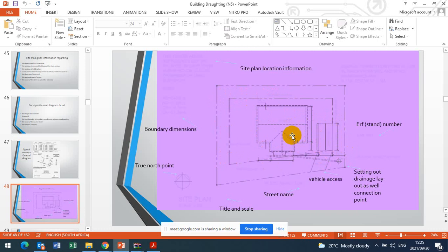So you must make sure you do this, and this is the roof edge layer. You see the dashed lines around the house. It is the roof edge. And this roof is called the Gable-End Roof. G-A-B-L-E. A gable-end roof is a pitched roof. It slopes only on two sides, this side and this side. Here it's a gable end, it's flat here and there it's flat. When we come to this corridor here, it's got a slope on the right and on the left. It's also a gable end here.